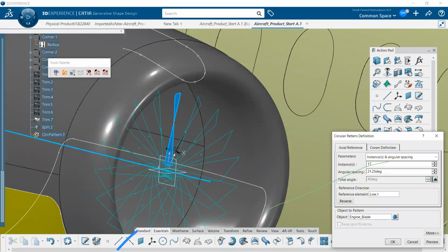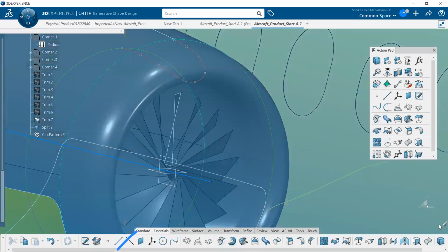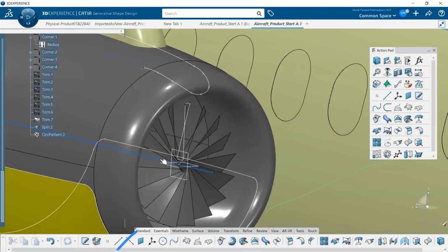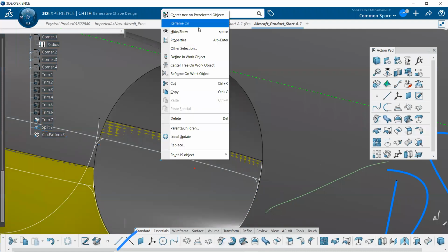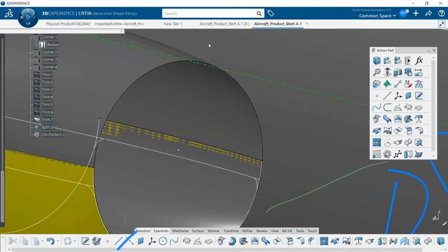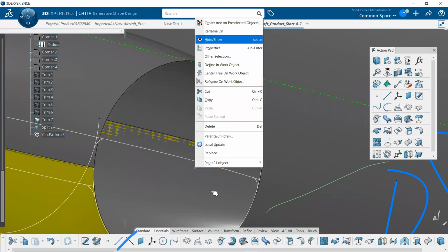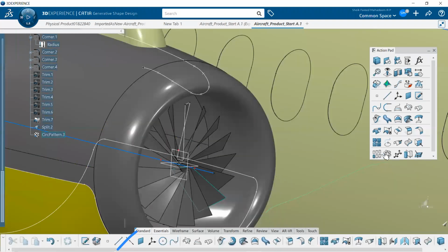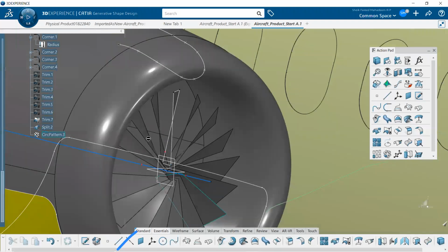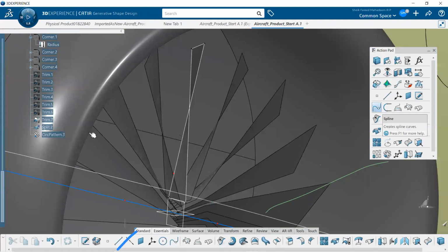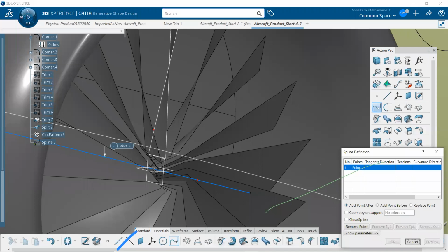Now in the middle there will be a propeller head. To draw this one, I need the reference points to create the spline first. So what I did is I selected point 1, hide and show, point 2, hide and show, point 3, hide and show. Then go to the unhidden parts. You can see there are 3 red lines. I just created the spline, selected this one, selected this point, and then selected this point. Click OK.